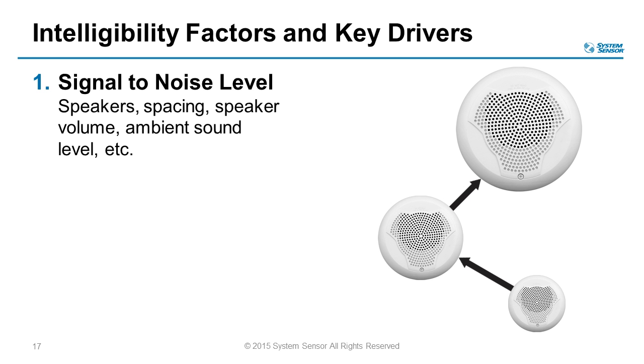The characteristics that drive the signal-to-noise ratio are the speakers that are being used, the type of speakers, how they are spaced, the volume or the tap setting that they are set at, and of course the ambient noise levels of that space.